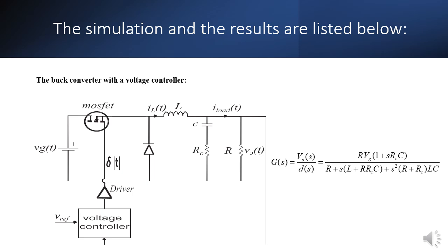And also, by using state space averaging during MOSFET on and MOSFET off, a linear time invariant model of the buck converter is generated in this section. The state space description of each of these systems is first developed, and a converter can be thought of as switching between various time invariant systems.